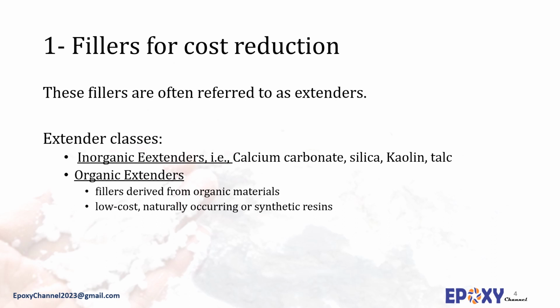Similar to calcium carbonate, silica is an abundant mineral found in crystalline form, quartz, and amorphous or diatomaceous silica. Silica is used more extensively than quartz because it provides fewer machining and abrasive problems. Although it is an excellent additive for increasing viscosity, diatomaceous silica has a low oil absorption and very large surface area. Therefore, it cannot be easily incorporated into formulations in high concentrations.